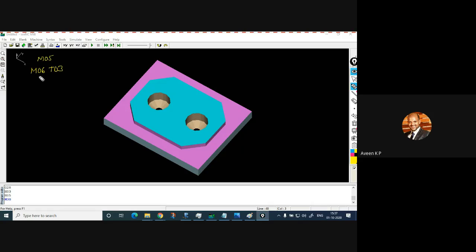Okay. And when you add the cutting tool, you make sure that you compensate G43 H3. So define the Z height, lift the cutting tool, Z100. I have lifted the cutting tool. Later, I will position in the work coordinate, the same coordinate G54. I will use rapid movement. I will position exactly here.